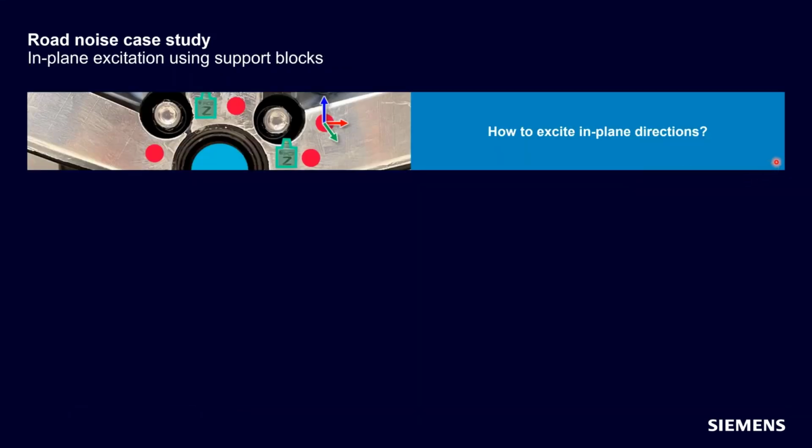Now, so far, I've only talked about the response points, so I need to briefly discuss the excitations, because this is actually a bit more tricky. For the excitations, just like for the responses, we want to measure as many degrees of freedom per point as possible. And for the normal direction, the green arrow here, that's quite easy, I would say. You can always just hit the structure with a hammer to excite this green direction. But the so-called in-plane directions, which are the blue and red directions here on these points, are much less straightforward.